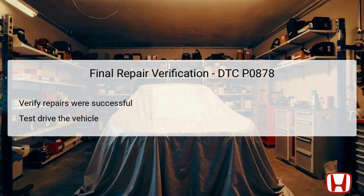Following this examination, a test drive of the vehicle should be conducted to ascertain whether the previous symptoms, such as the MIL illumination and transmission performance issues, have been rectified. During the test drive, attention should be paid to the behavior of the transmission, particularly during gear changes and under conditions that previously triggered the DTC.